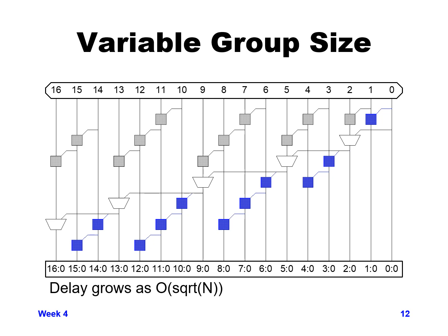Now, a variation on a carry skip adder is a carry skip adder with variable group size. So the one we looked at in the previous slide, we took 16 bits and we broke them up into 4 groups of 4-bit segments.